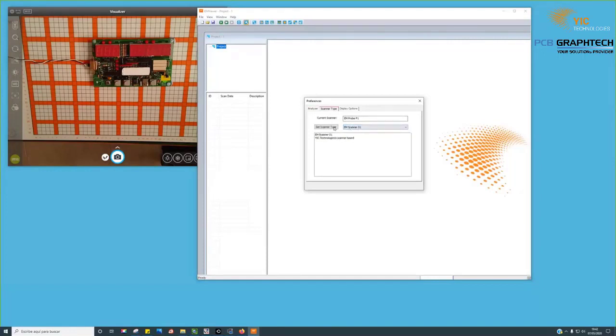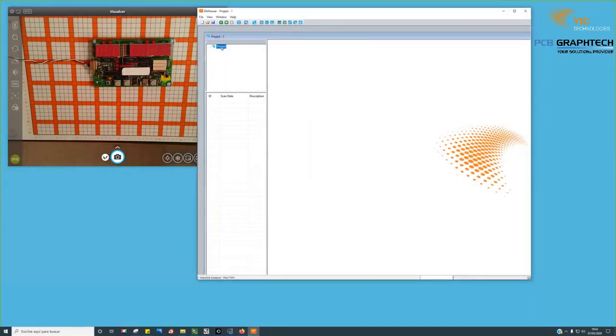So let me set the scanner, and then you need to connect the radio frequency output of the scanner to the spectrum analyzer. Let me check that it's connected correctly. And then, when you have connected the EM scanner to the spectrum analyzer, you can create some specific nodes. You can create a spectral, a spatial, a spectral comparison, a spatial analysis. Let me go to a spectral.